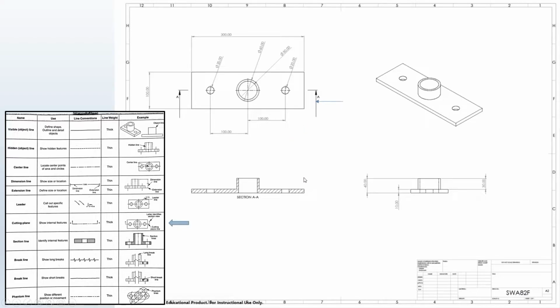and then that's going down here, and this is that piece cut in half and then flipped like you were looking at the cut. So this shows you some of your internal features. And in this case, because this piece is symmetric across this plane, we can see across the plane that we cut the center of both of our holes and this hole in the middle as well, and we can see how this dimension works.